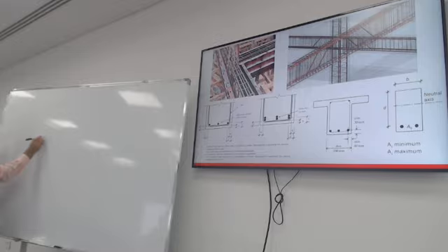So at the very early stages under the elastic load, you will have compression stress at the top and tension stress at the bottom, and then the distribution is going to be linear. All right? This is tension, this is compression. The amount of tension that concrete can take is very small. Very quickly, this will reach a stage where concrete cannot take tension anymore, and this will result in a crack.